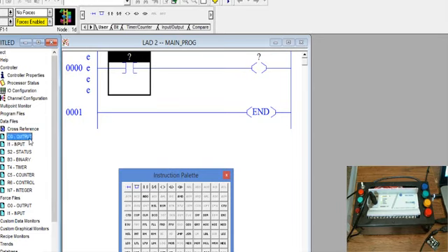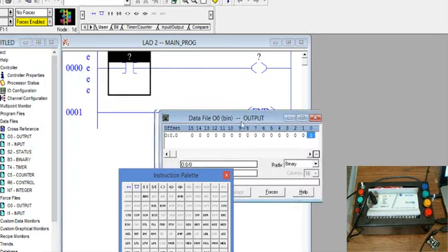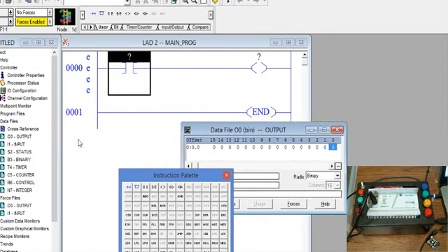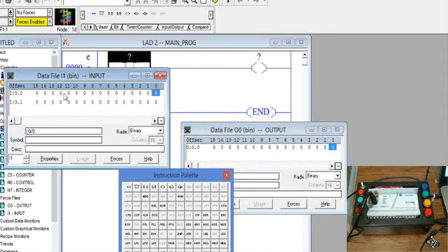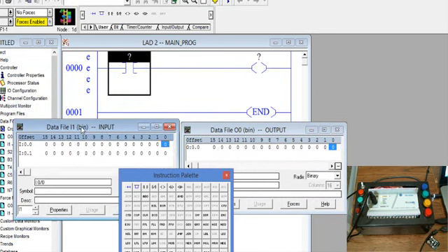In other words, there's always a need to address, and addresses are the ways to label what each of the elements, or inputs and outputs, on the program are. The labeling is very important because it tells the controller where, in the physical points of contact or terminals of the controller, that component is connected.